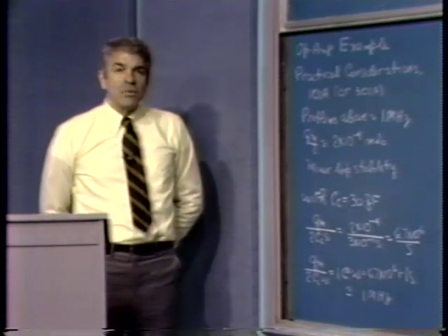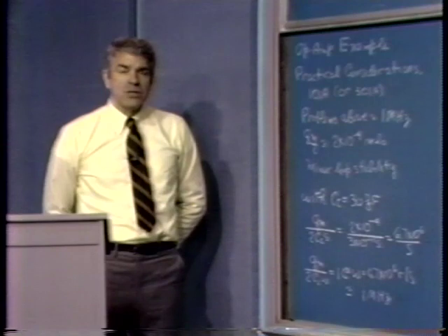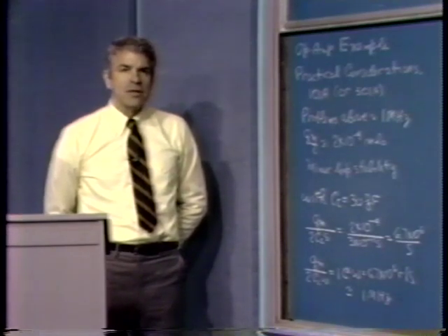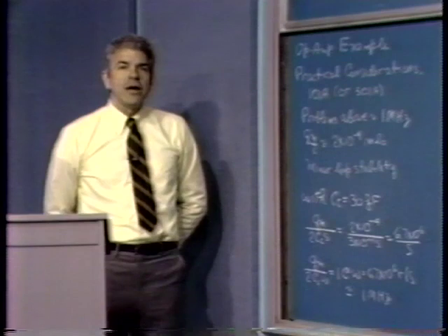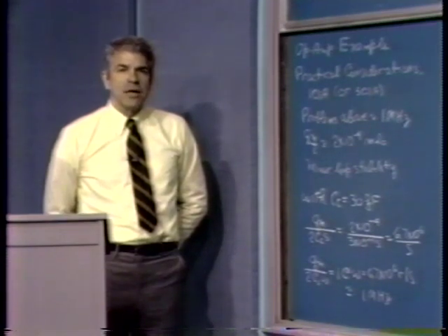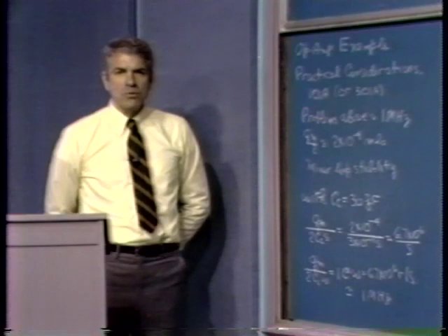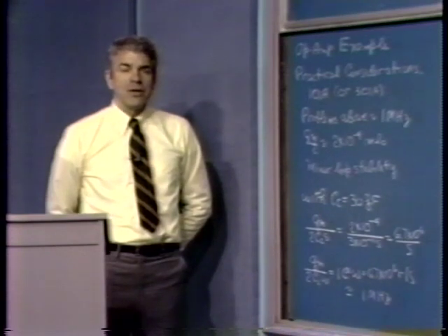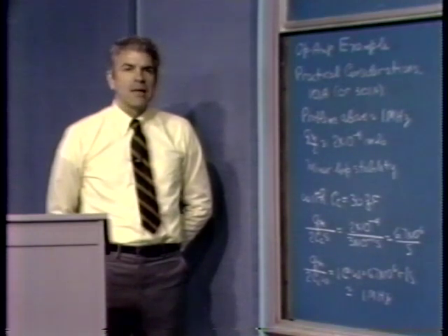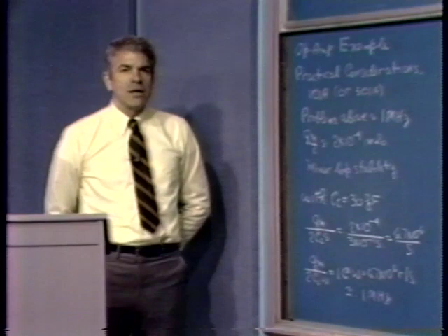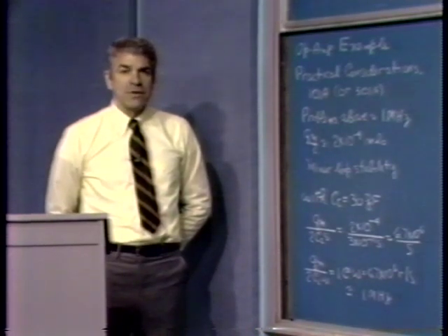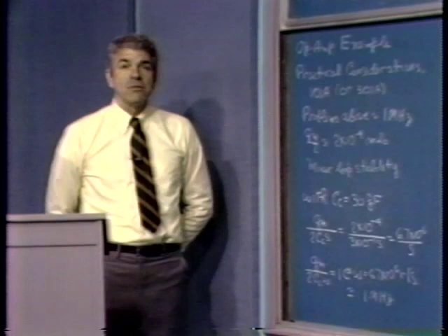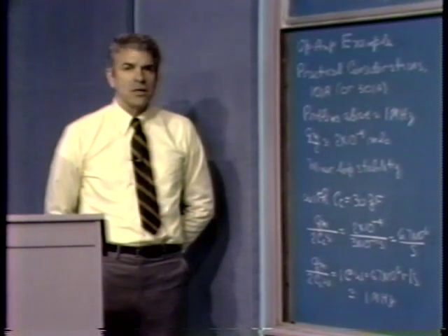One kind of compensation that we can implement very easily in minor loop form is so-called single pole compensation. What we do there is use a single capacitor as the compensating element. That's sort of a degenerate case of a two-port, and if we go through the numbers, we find out that the transfer admittance for a single capacitor is simply equal to the value of the capacitance, let's call it C sub C, times S. Consequently, when we evaluate our approximation to the open loop transfer function of the amplifier, it would be G sub m over 2 times C sub C S.